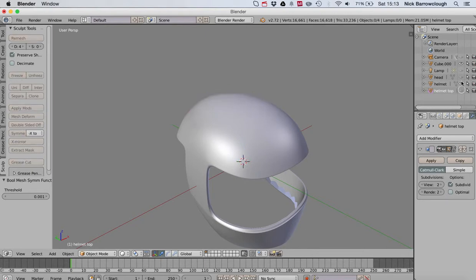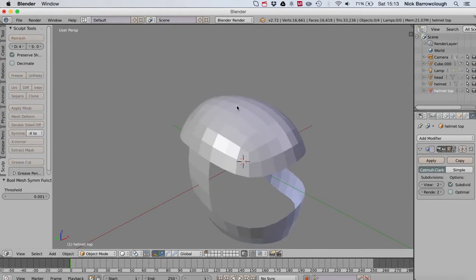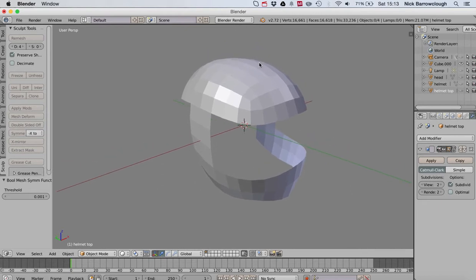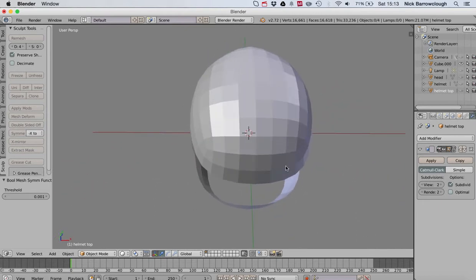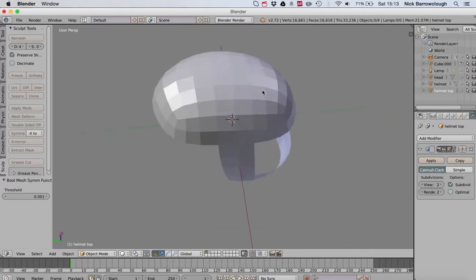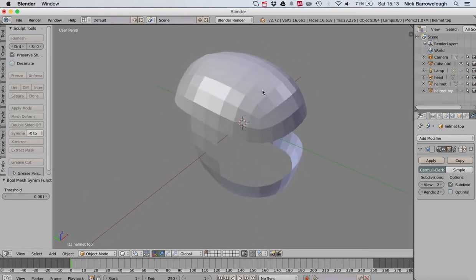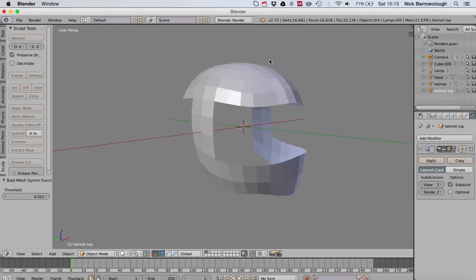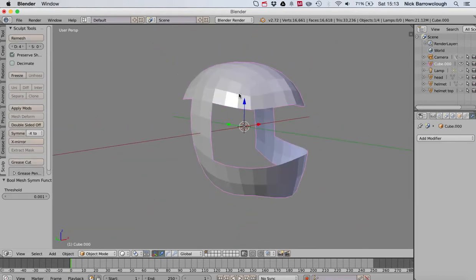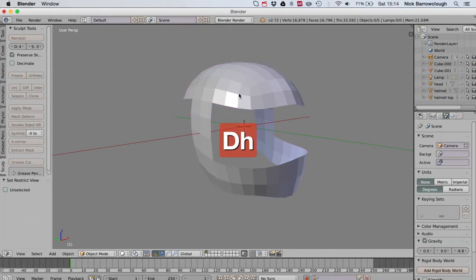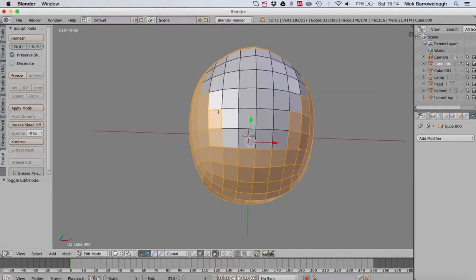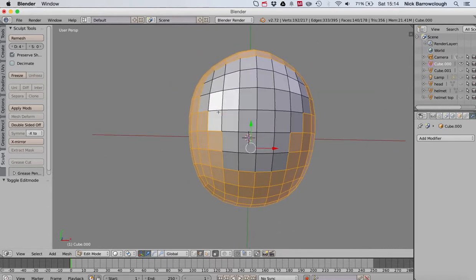Let's hide those, and then we're back to our basic helmet shape again here, and we're going to take a part of this which is going to be used then to form a section which goes on top of our object. So again I'm going to duplicate it, hit H to hide it, we'll tab into edit mode. Okay, so that's what we had selected earlier.